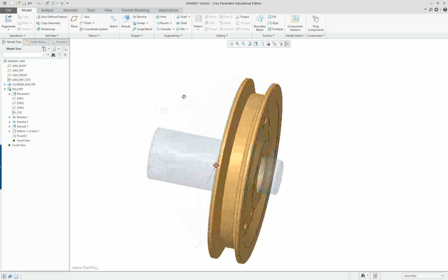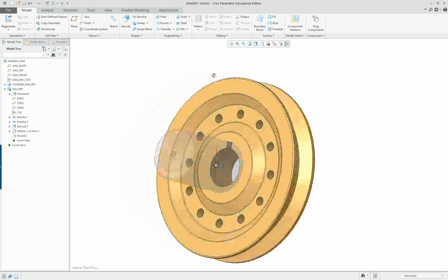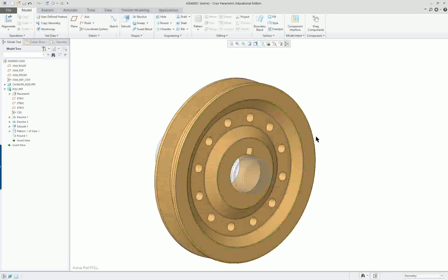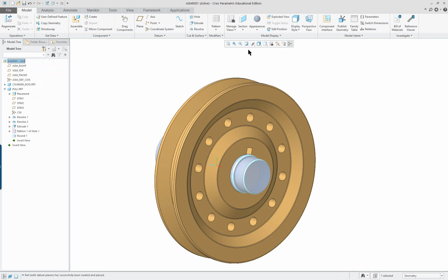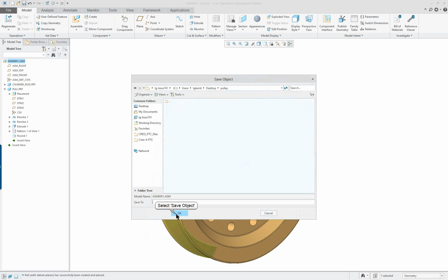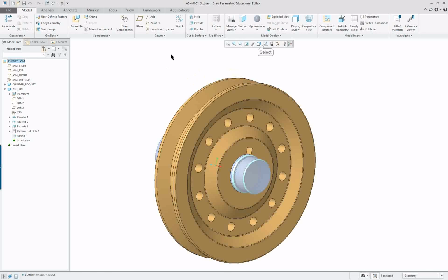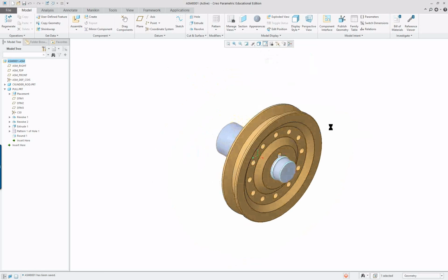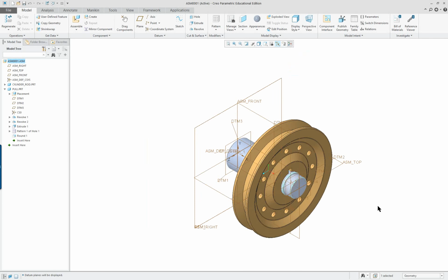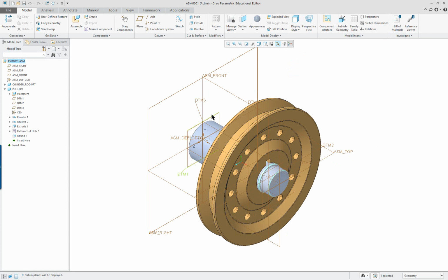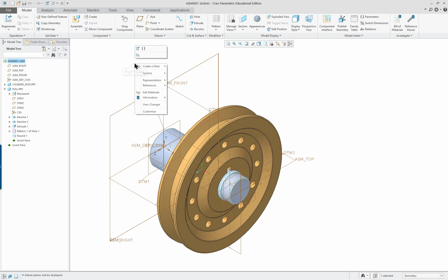All right. So we have our first component modeled. Top-down design. I'm going to go back over to my assembly here and activate it. You should save it at this point, obviously. And go back into my standard orientation and turn on my datum features like so. So the next one's going to be the pulley. Right mouse button. Should be active here.